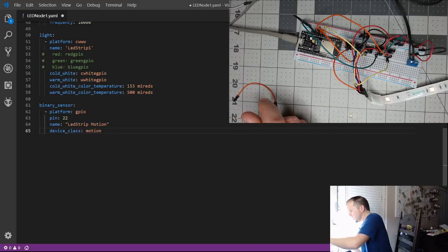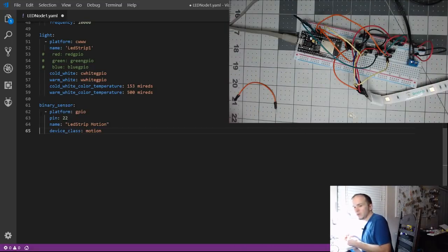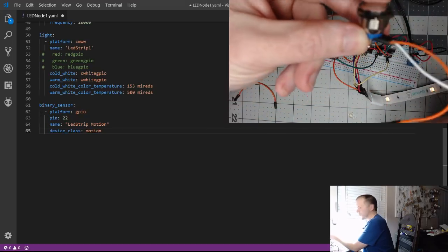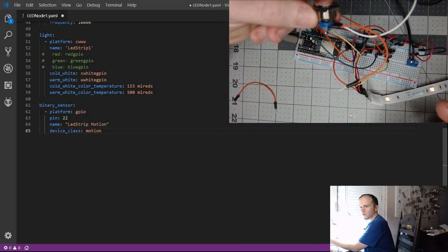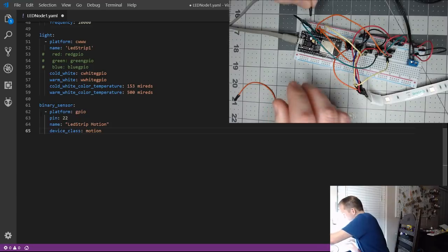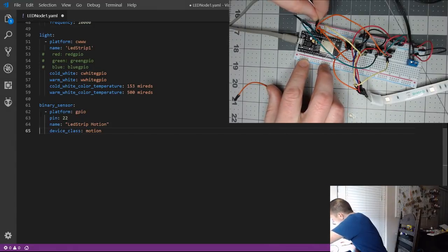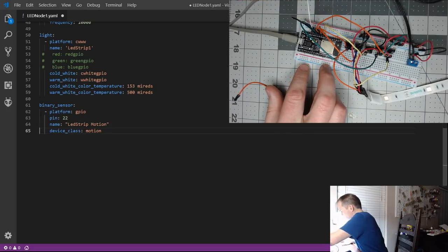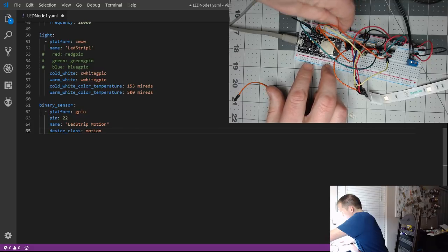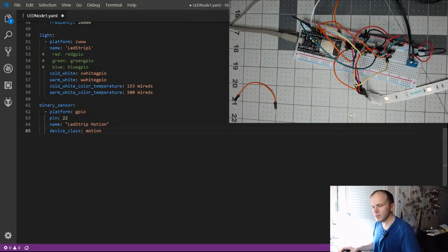So let's see. I had just a button here. Since we want to do that temperature sensor right quick, I had just this simple little push button, and I threw 2 jumpers on it before the video. We'll see if we can just pop that to ground on, let's do GPIO 13. Maybe have to go high or low, but I'm thinking probably want to go low with this thing. Definitely don't want to go high with 12 volts into there. But I do have 3.3 volts over there.